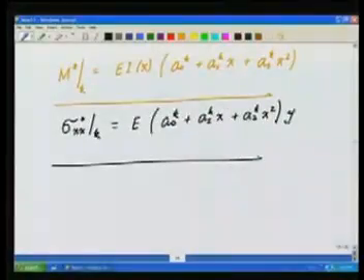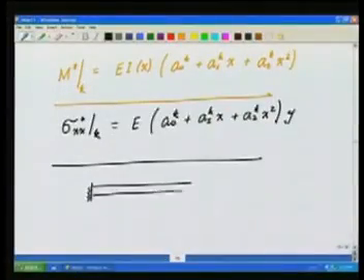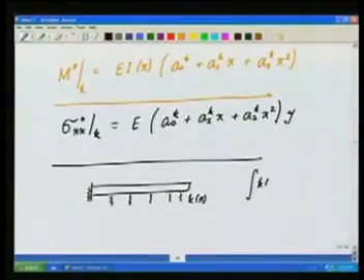Okay. So now you see that we have been able to reach a proper procedure of solving for the actual bar problem and actual beam problem. Now, in general, I could also look at some extensions of this. Maybe my beam is sitting on an elastic support, that is, on a distributed spring. So with this I will only change the stiffness matrix part, that is, to the stiffness side I am going to add k of x V FE into W dx.